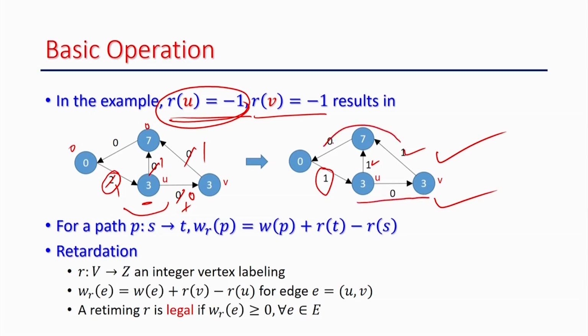So, the maximum delay will become 7. So, I understand that. Okay. So, this is how we will do it. We consider a variable R for each register, and we try to find a set of inequalities or constraints which will be satisfied by this R, okay, that we are going to discuss. And then we try to solve those inequalities using the shortest path problem, which will give you the values. Okay. This is the overall approach.